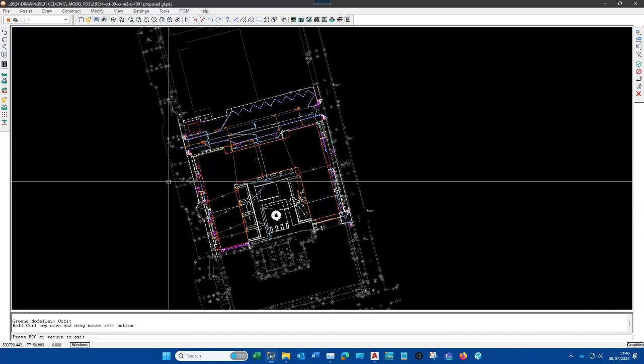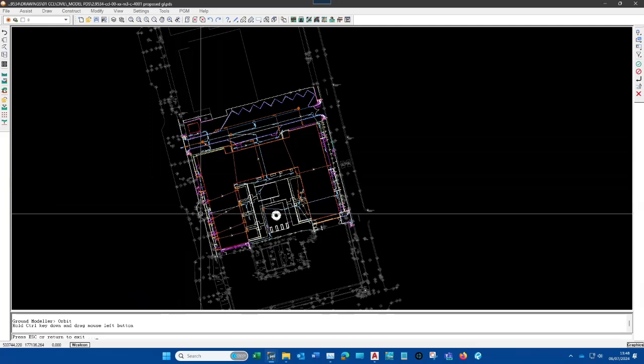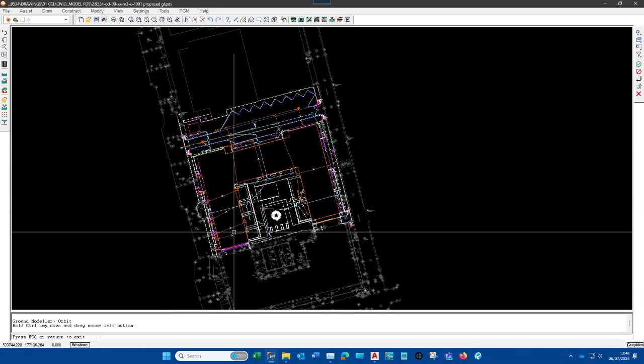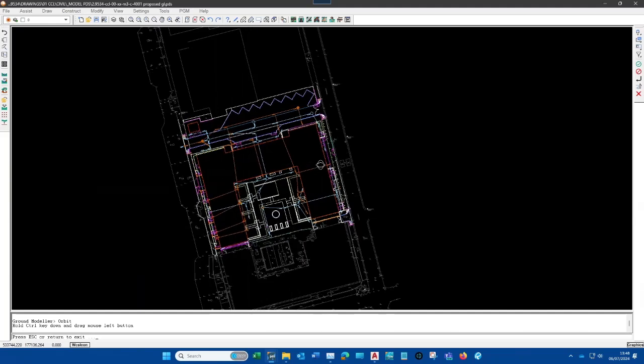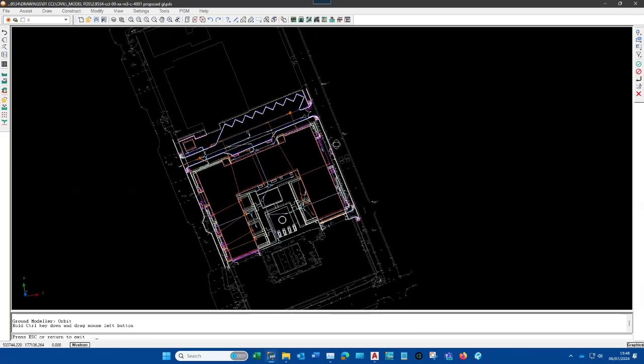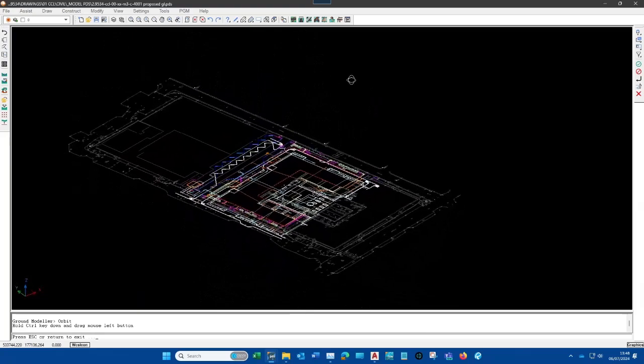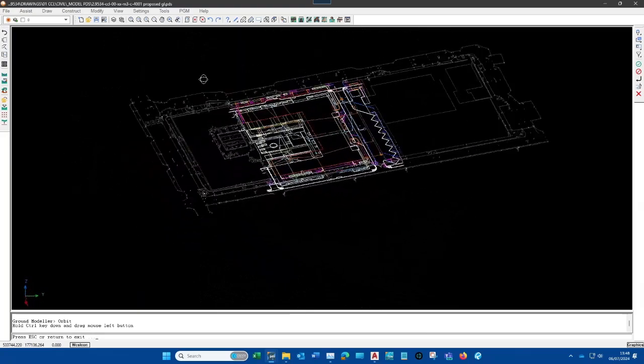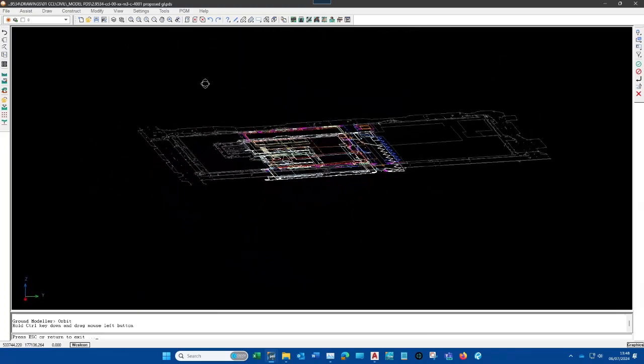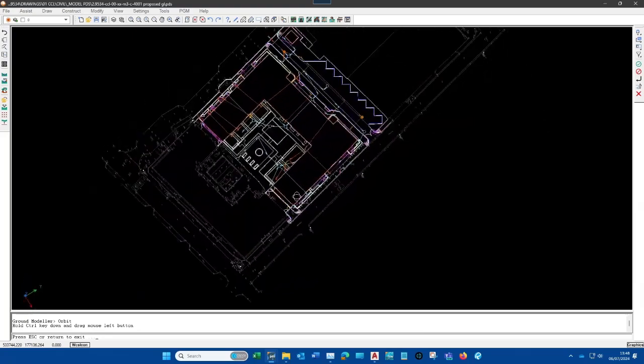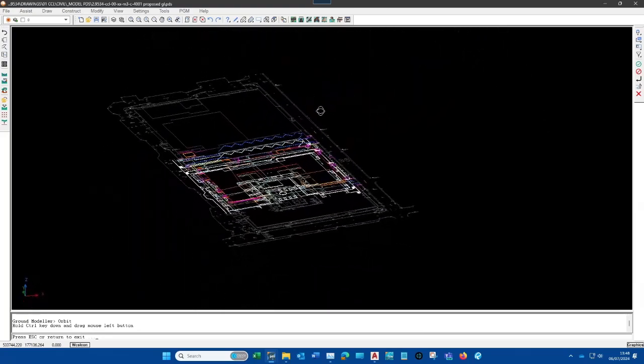where we can hold the control key down and you use the left mouse and you click and you hold, and there the cursor's changed to those two circles interacting to each other at 90 degrees. And if I move the mouse, you can see it spins everything around, so you can see how it looks, which is really important if you got lots of embankments on a site or a really curvy one.